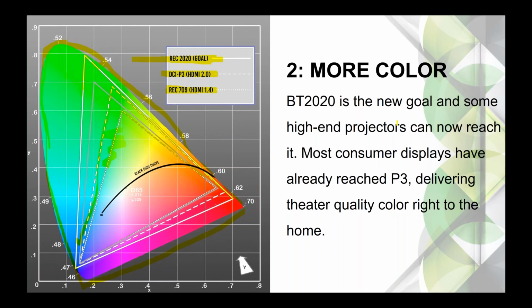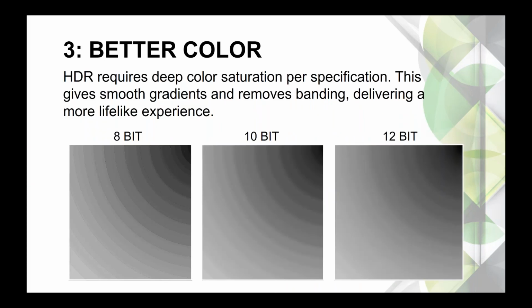That is the beauty of BT.2020 and wide color gamut. The other thing that we've gone to now is we've gone up in bit depth. So everything to this day, like a Blu-ray player, has been 1080p, 24, 4:2:0 or 4:4:4, but mostly 4:2:0 and 8-bit. 8-bit gives you 1 to 255 choices, so that's your bit depth. An 8-bit system is 255 steps of gray or red, green, blue, cyan, yellow, magenta.